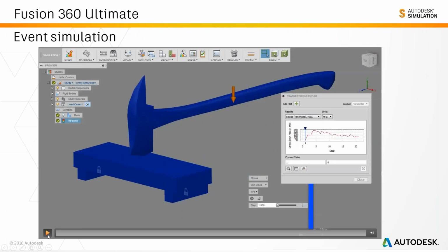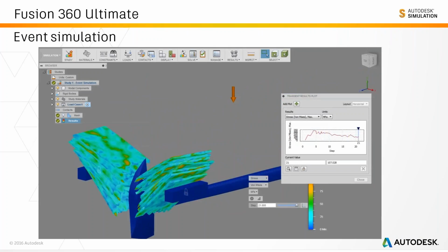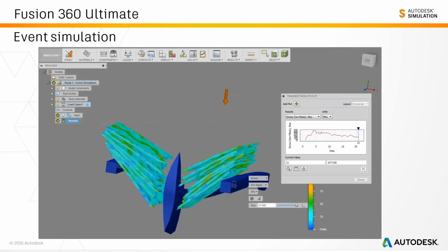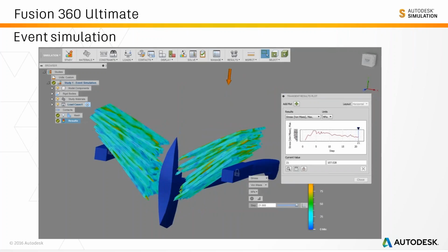Here's a bit more funnier example here. An axe going through a number of plywood or plastic boards. You can see how by specifying an initial acceleration, we actually don't need to start the analysis all the way up, high up above the part impacted.